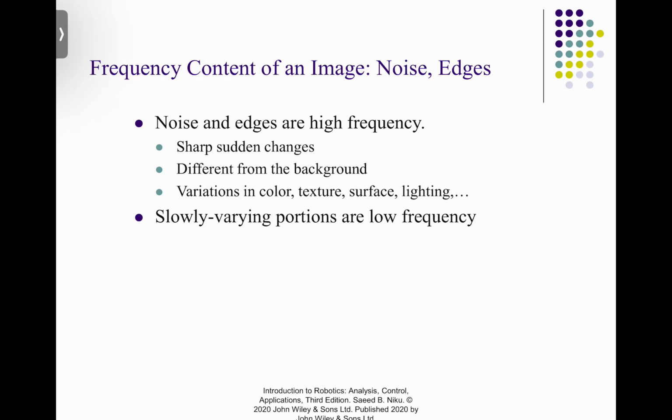That noise signal is inverted and then added to the headphone music, so that the contamination cancels the whole thing. So you get a clean signal. That is how a noise cancelling system would work.